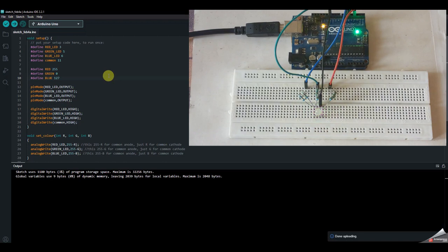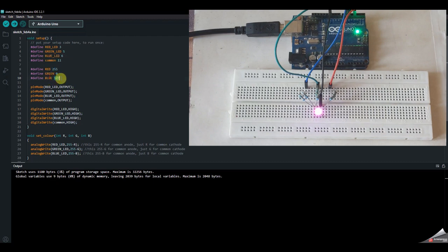As we can see, the blue color in the first few seconds doesn't glow, and it only glows after some time. This is because the blue will not get sufficient voltage, because already we are giving only less intensity for that, and a PWM on top of that will not even glow the blue color. So that's the reason we can see flickering of the blue color.